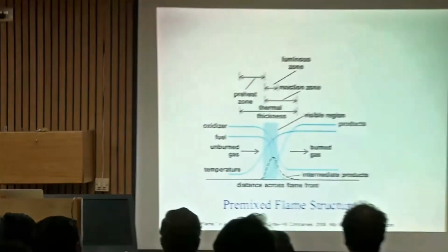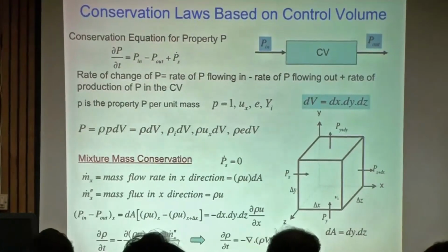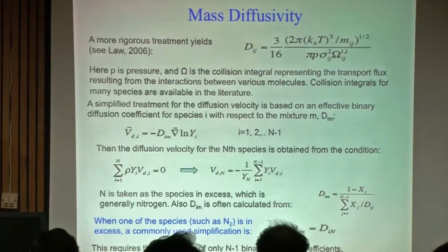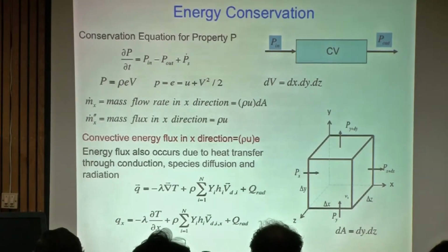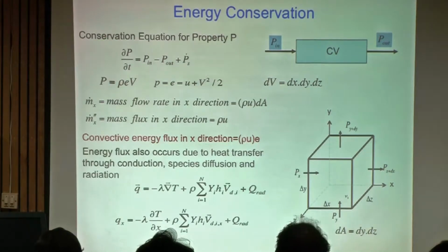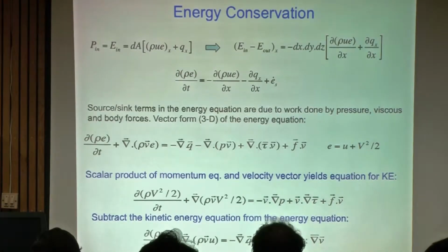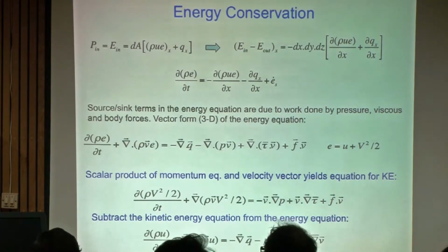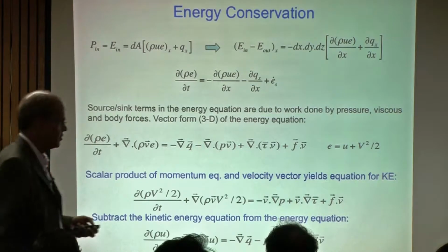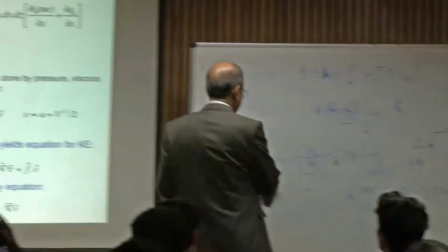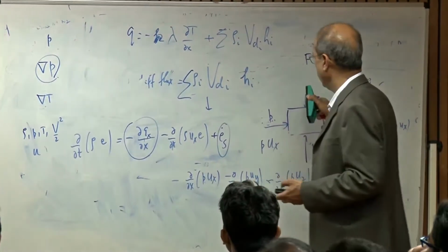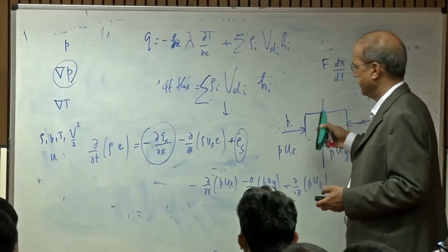Now we can go back to the energy equation we were in the middle of. We did this part. We were considering the work done by the pressure forces and then the viscous forces. For viscous forces, you again have the normal stresses and the shear stresses, but the work done will be similar, because work done is just the scalar product of the force vector and the velocity vector.